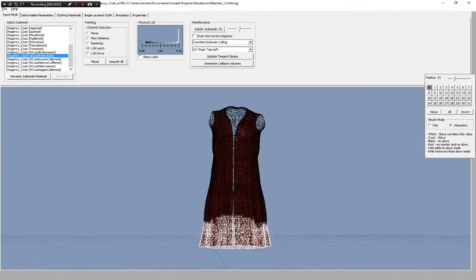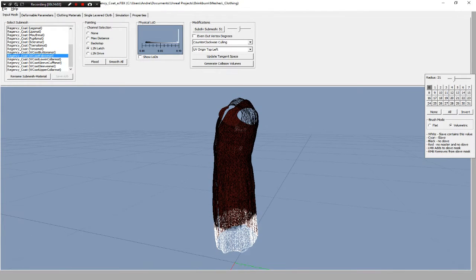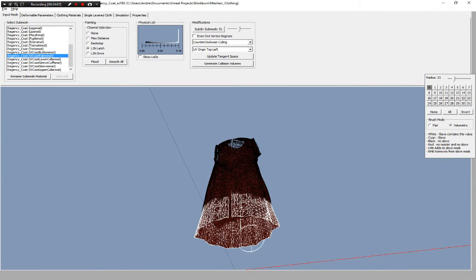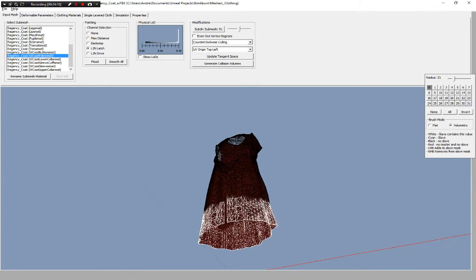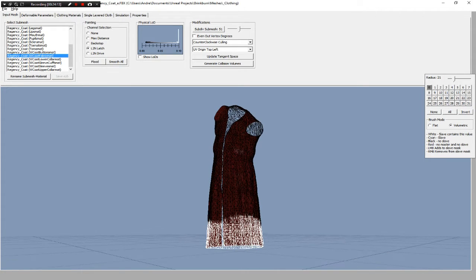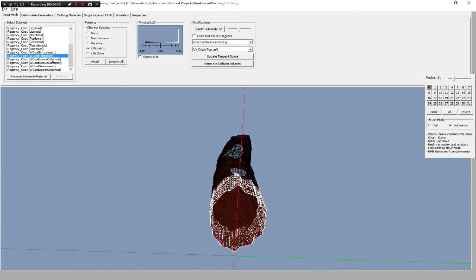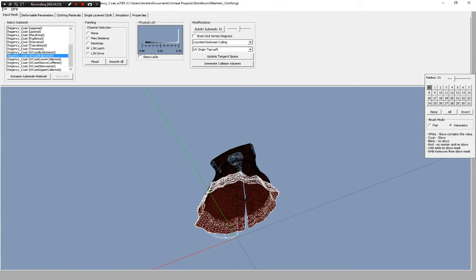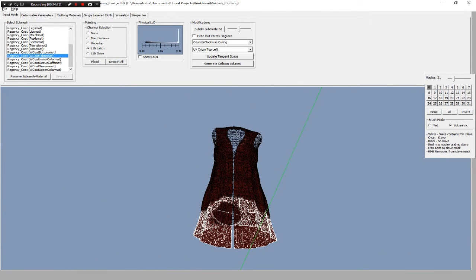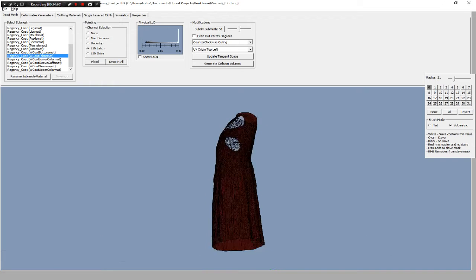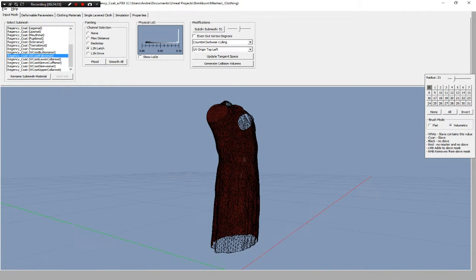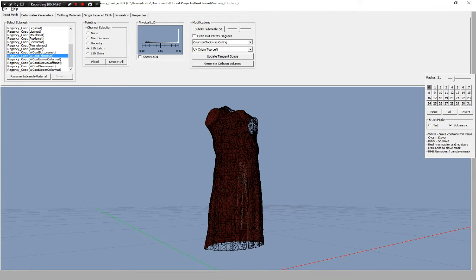And this will mean that you can then deactivate the verts on the outside and only have your inside working. What this will do is stop the outside verts from being calculated because they're attached to the inside. Only the inside verts will be calculated whilst the outside ones won't. So this will help performance from the get-go, and it's just better to have fewer verts being calculated as a general rule. And it'll also make your clothing physicality work better because then those verts